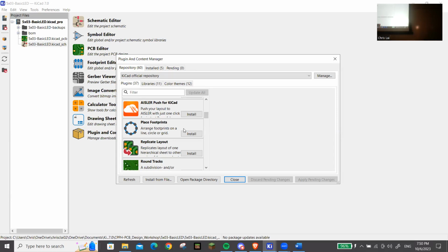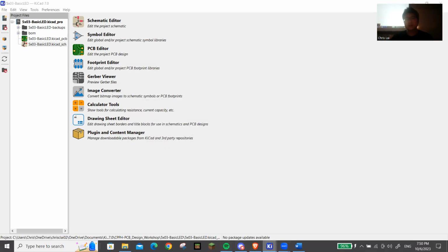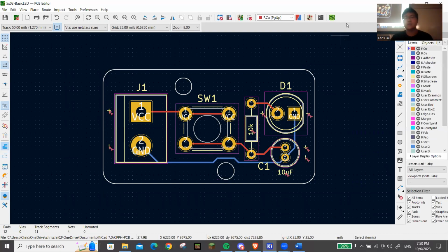It generates a bill of materials. So I'll show you. Again, bills of materials are really useful for figuring out how to make your PCB come to life. So again, to generate it, all you've got to do is go to your schematic here, press this button on the right, and that generates an interactive BOM for you.